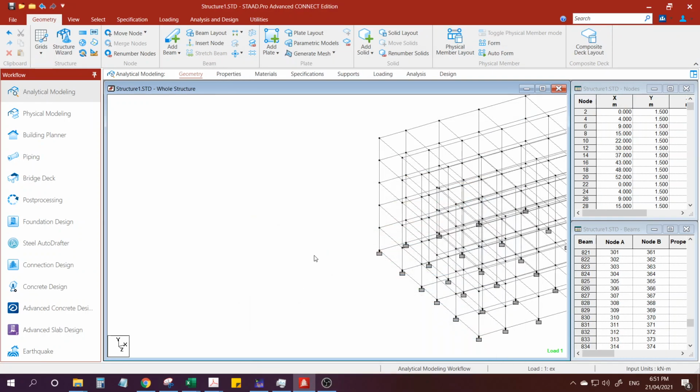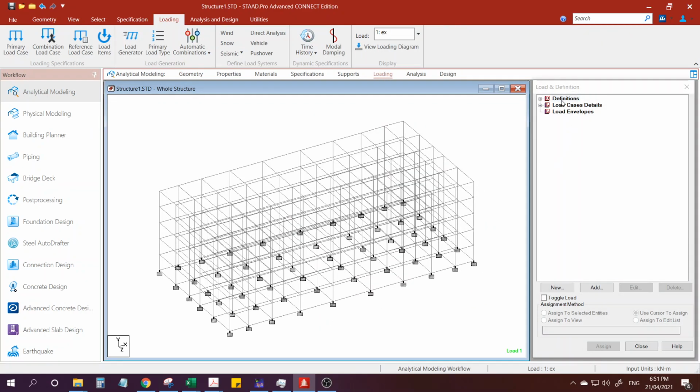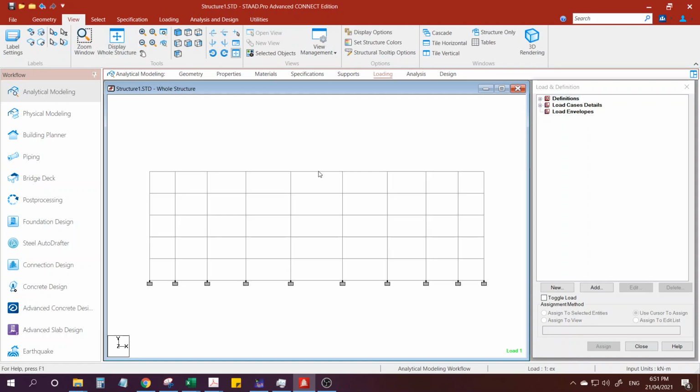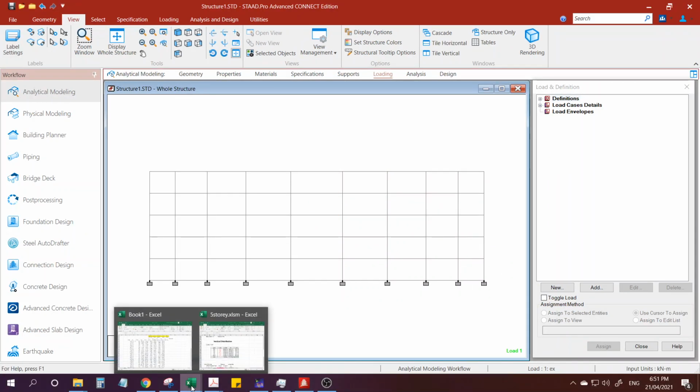Next, let's proceed to the loading. Now as a trick, I need to quickly insert the weight per floor. So you can imagine that if I view this front view, I need to insert the weight per floor in this model. And of course that should follow the weight that we lumped or got from our spreadsheet. For example, here, this one.